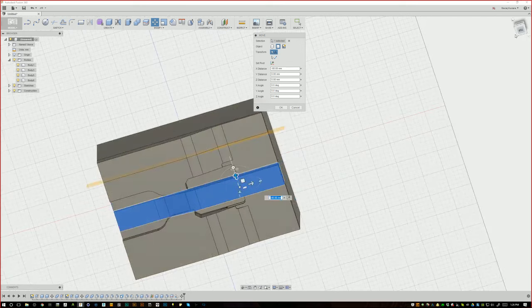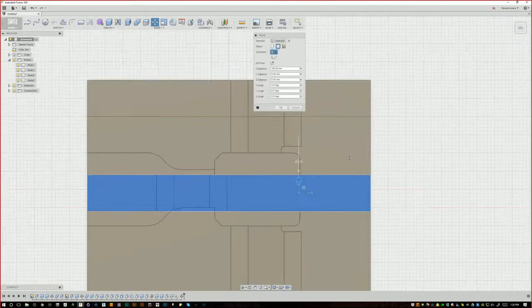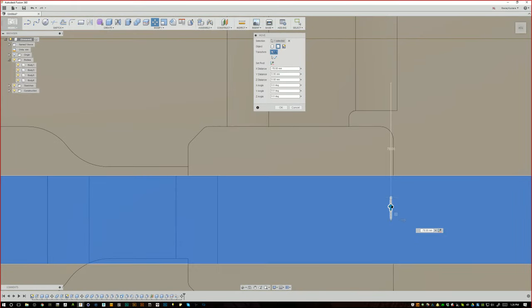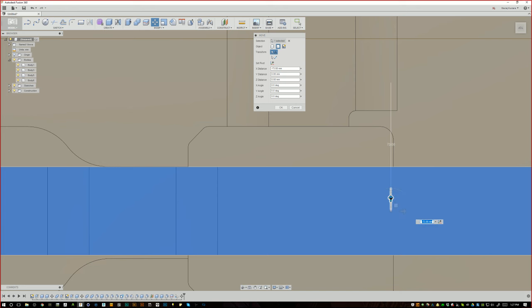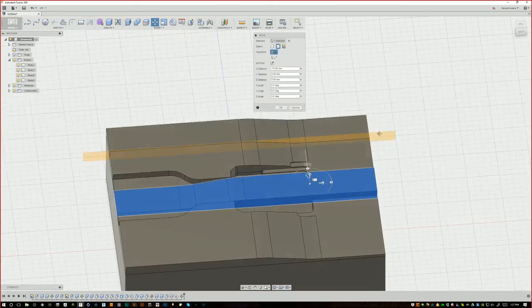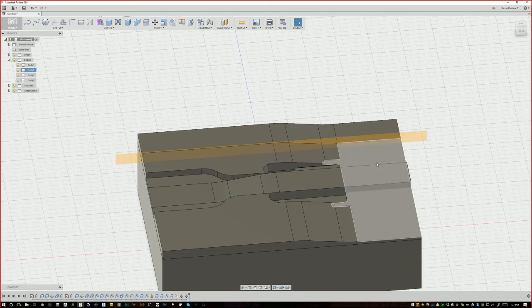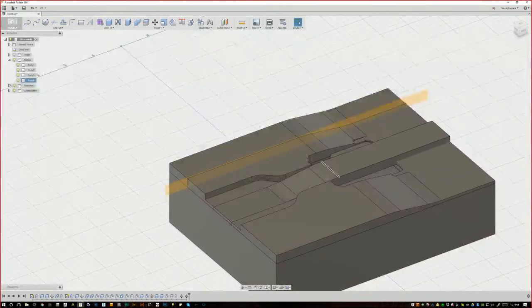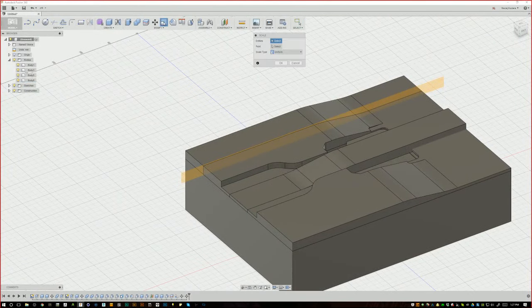Yeah, that's something I was actually teaching in my futuristic character design class, where I would model something in Max, for instance, and bring in the mesh, and then use that mesh to create a T-spline body. But the major constraint was that it had to be basically a perfect quad mesh. If there was any triangle, it would not work at all. Yep, today it's only quads. Tomorrow we will be everything, right?